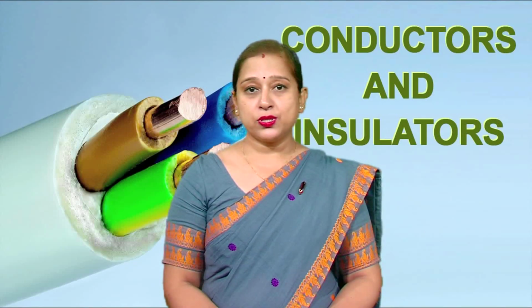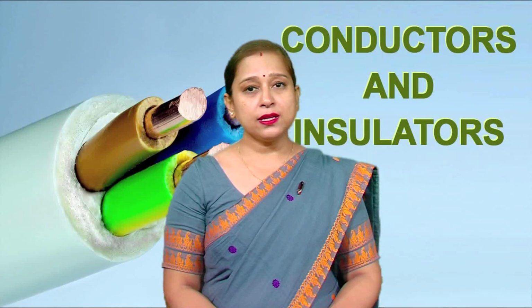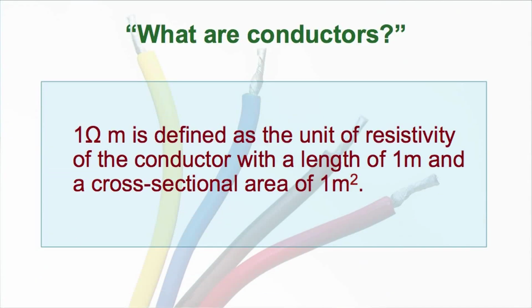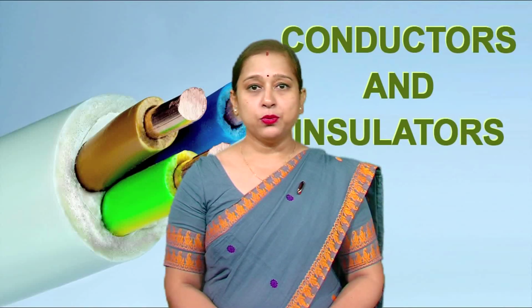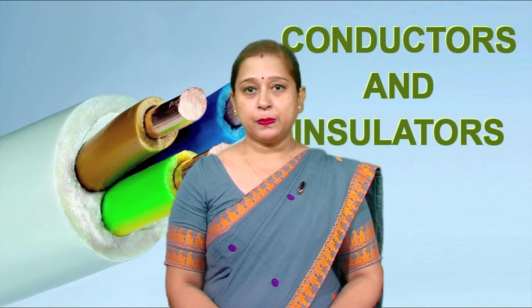Conductivity is the inverse of resistivity. The SI unit for electrical resistivity is ohm meter. Then what is 1 ohm meter? 1 ohm meter is defined as the unit of resistivity of the conductor with a length of 1 meter and a cross-sectional area of 1 square meter. Resistivity is the value that characterizes a given material. However, it is affected by temperature.